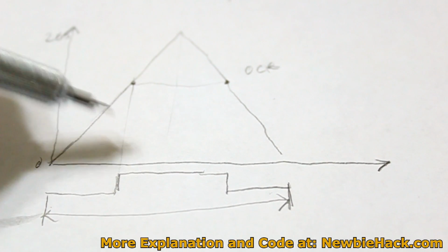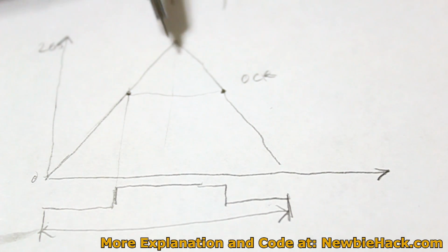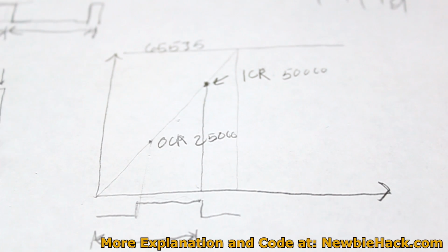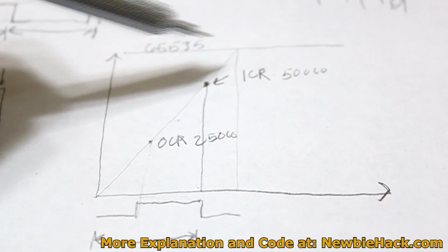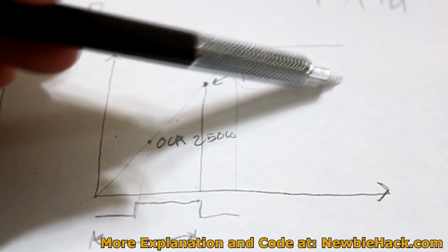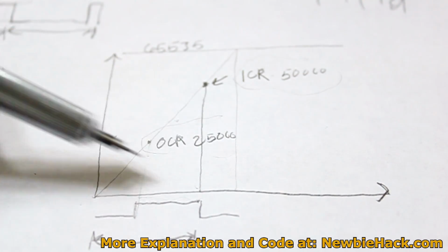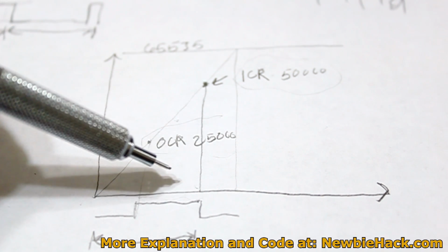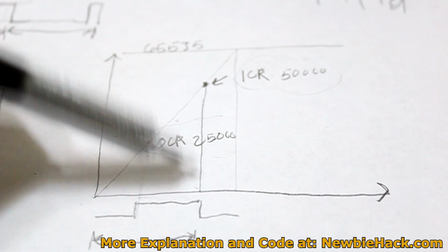We can do this with the 16-bit as well, where the top value would be 65,535 or whatever you set in the ICR register. When we do program for the servo, you will see, using the timer and just applying a couple numbers, the ICR number and then the OCR number, and doing some control, how effortless it is to create control for a servo with a microcontroller.